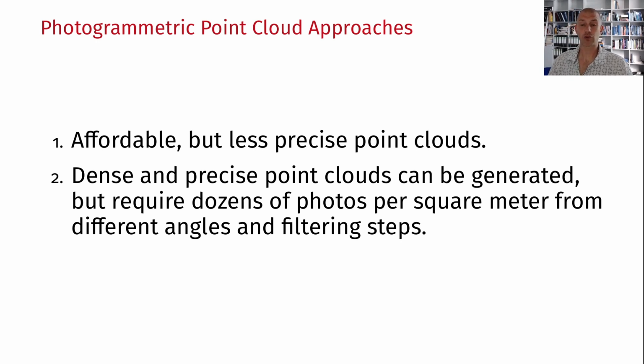In order to generate precise point clouds through photogrammetric approaches, you need to work carefully and calibrate your devices very carefully. You can generate very, very dense point clouds, and I'm going to show some of those, but they often require many photos per square meter and likely some post-processing.